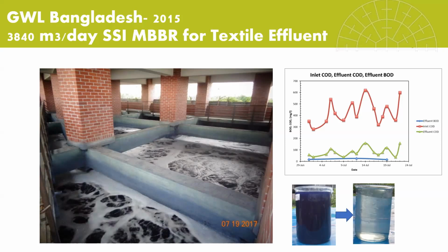So with this particular facility, it was a holistic approach. We did look at the primary system design. We looked at equalization design. We looked at the biological system and the existing clarifier system. And basically what we came up with was an MBBR process, fairly conservative loading rate.